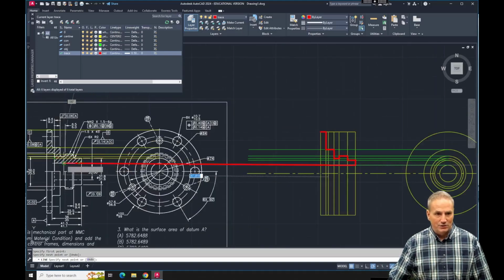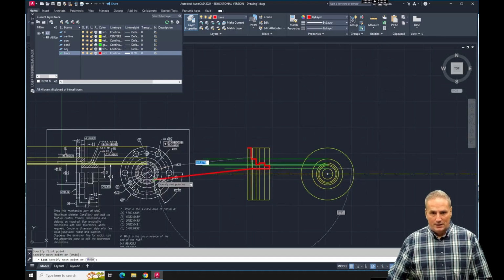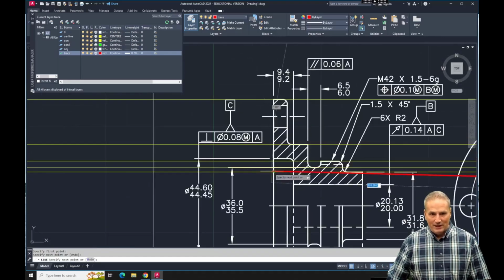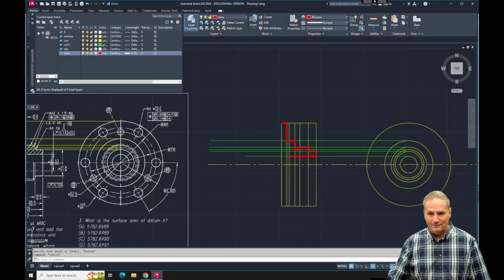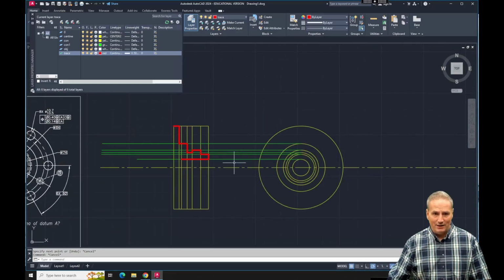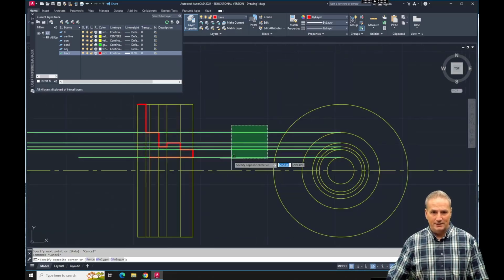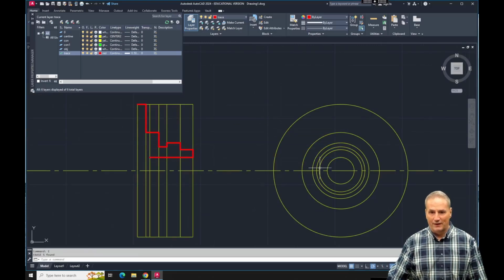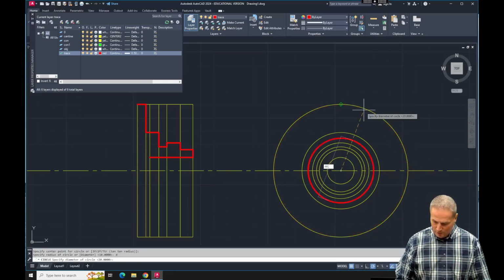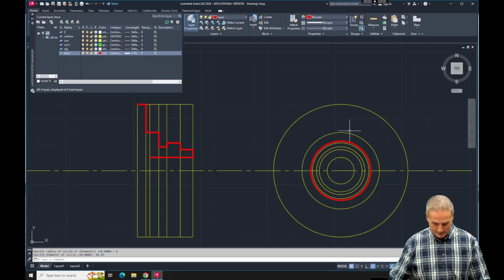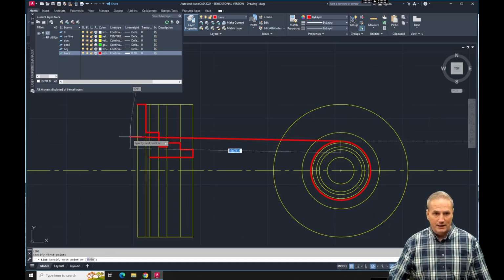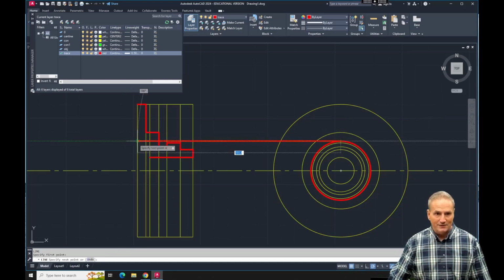So now we just need to come up, and to come up we have to have this circle drawn now. So we have to have that, and again that's going to be a smaller, right? So 44.45. You know, at this point, if you're like, hey, all right, things are just getting a little hectic, I don't need this anymore, maybe let's get rid of that, right? So whatever works best for you. But we can say circle, diameter 44.45, I think it was. L enter, and I can just bring that over as a line, I guess, for now.